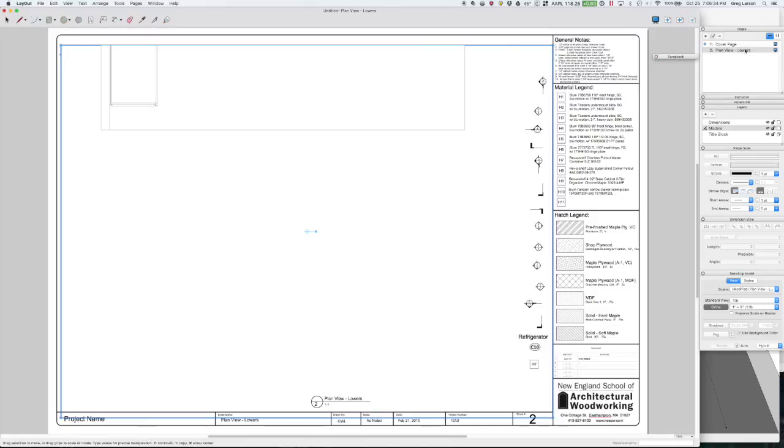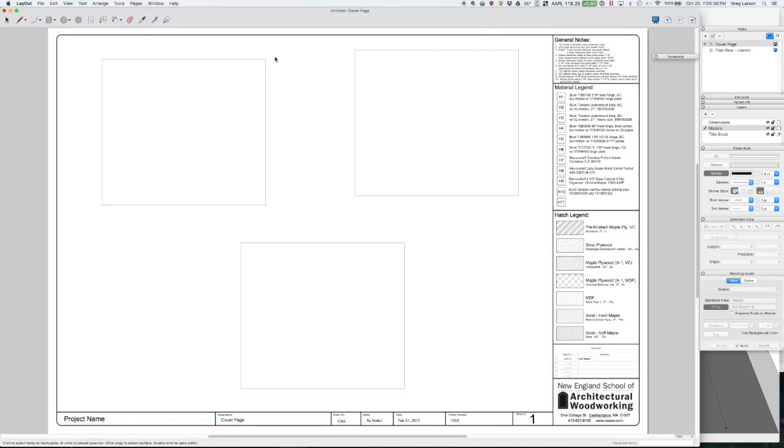So what these blue rectangles are called viewports. So each viewport can be pointed to a scene back in our original Sketchup file. So what we've done is link our Sketchup file to a layout file. And what's cool is I can mix 3D views or scenes and 2D views or scenes in my shop drawings.